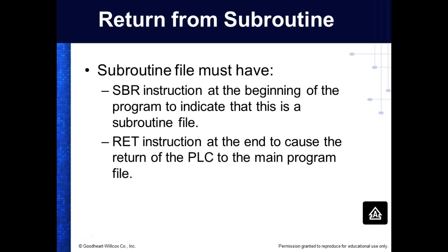Subroutine. And then the very last rung before the end, that's the rung that we don't specify. Anytime we create a program, it automatically puts an end instruction at the bottom, right? Then the last instruction in the subroutine should be a return. Are we okay? Okay, so far.